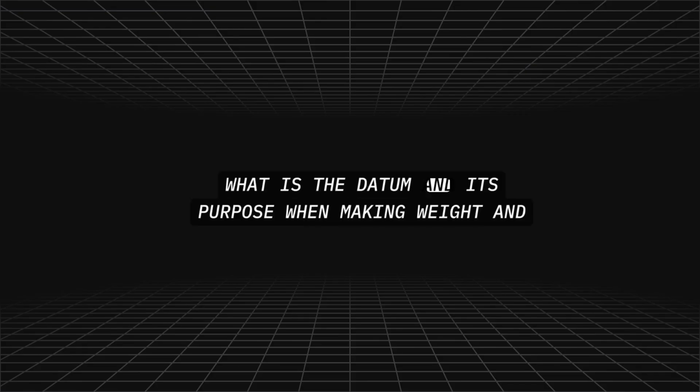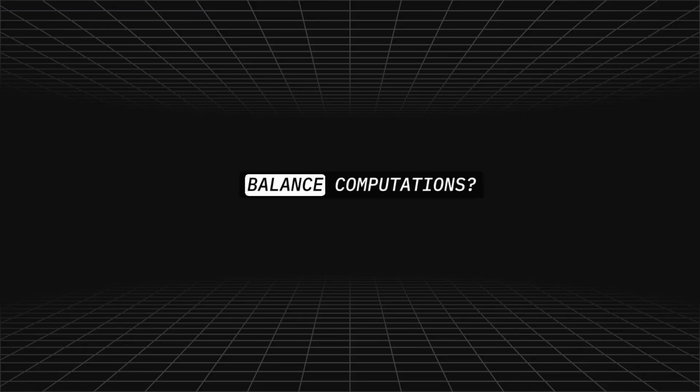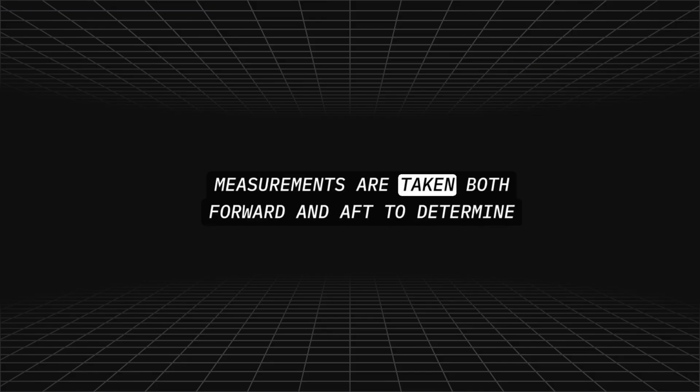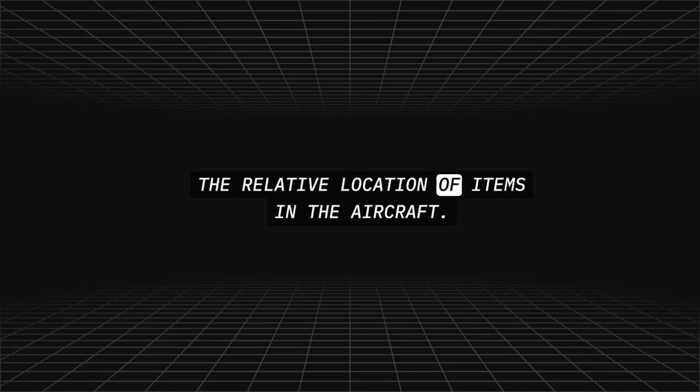What is the datum and its purpose when making weight and balance computations? It is an imaginary vertical line or plane from which all measurements are taken, both forward and aft, to determine the relative location of items in the aircraft.